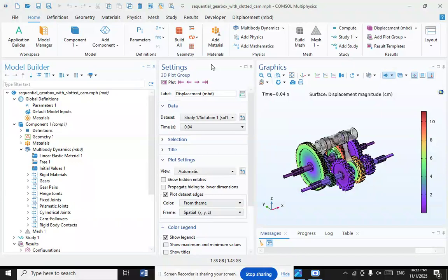And what about the internal shafts? A manual transmission has several shafts with various gears and other components attached to them. Most modern passenger cars use constant mesh transmissions consisting of these shafts: an input shaft, a counter shaft, also called a lay shaft, and an output shaft.